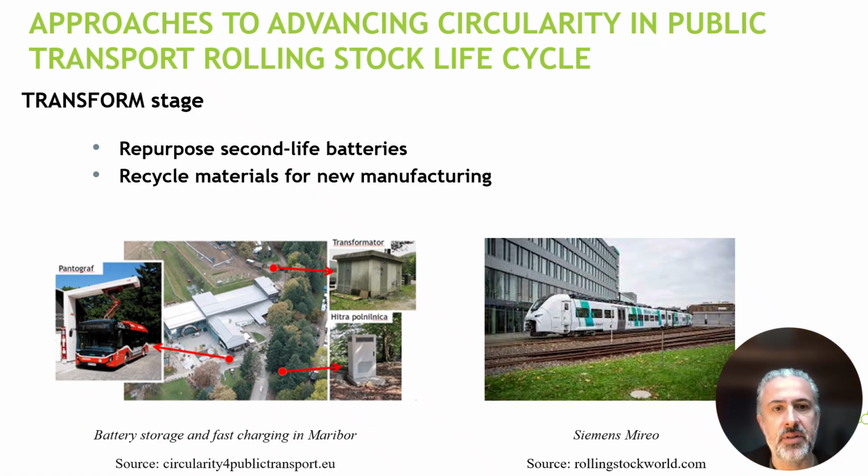Let's have a look at what happens at the transform stage. Repurposing second life batteries involves extending their utility beyond their initial application for other energy storage needs. The repurposing process is complex and requires different phases: testing and grading to determine their remaining capacity and state of health, disassembly and refurbishing, preparing the modules for new applications, and combining modules to create larger storage units suitable for different purposes. Second life batteries can be used, for example, as stationary storage systems for renewable energies, for grid support, and to power EV charging stations.